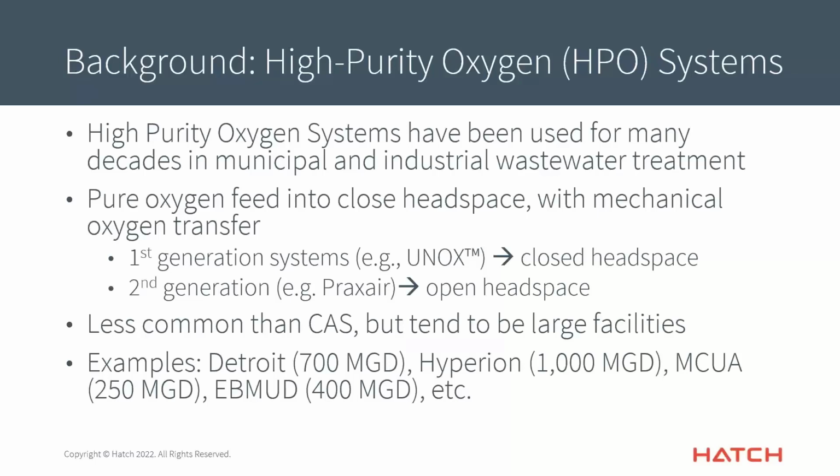I think UNOX is certainly the most well-known of those, and there are many of those still in existence. That is a closed headspace. So as I'll show you shortly, the idea is you have a plug flow activated sludge system, and then the headspace kind of has a lid on it. It's holding in all of that valuable pure oxygen gas, and then using mechanical surface aerators to get that oxygen exchange into the liquid. And then there has been a second generation of HPO systems that involve getting that HPO gas down into bubbles inside the liquid itself.